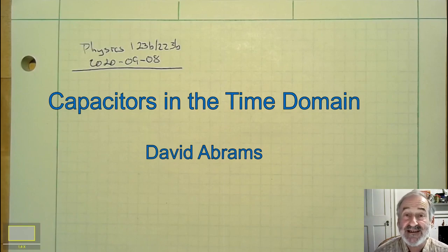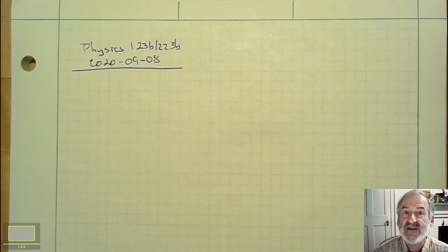Last time we looked at DC circuits, that's circuits that don't change voltage over time, and that's nice if we want to light a light bulb or run a motor, not very useful if we want to convey information, which of course is what this course is all about. So we need a way of creating time-dependent circuits, circuits where the voltage changes with time, and to do that we need a time-dependent element. Resistor certainly isn't that, and even the diode, while nonlinear, is still time invariant. So we need a new element, and that element is the capacitor.